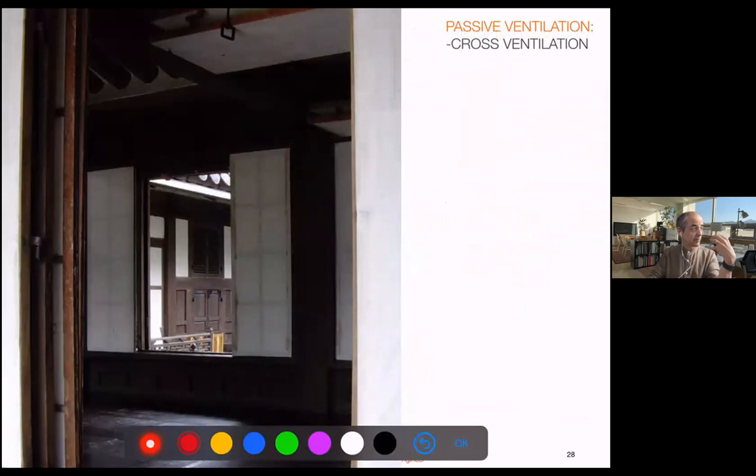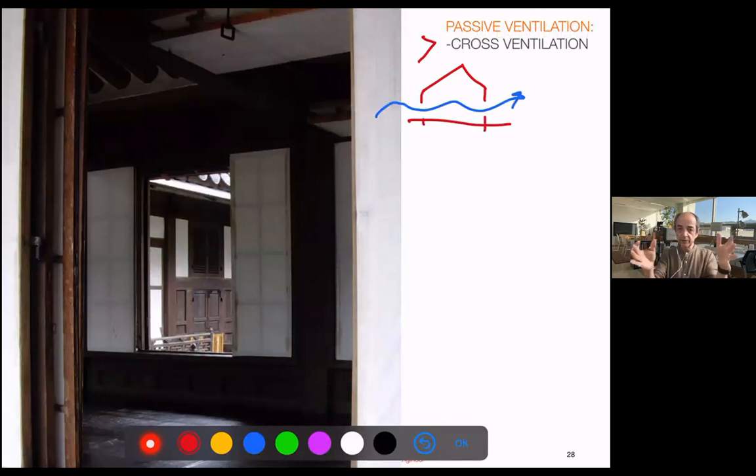Tips, especially for climates as extreme as Korea, in summer is the cross ventilation. So if you have a building and you can have the air crossing from side to side, you will always have some air movement. It will be easier for the air to renew. This is why rooms with two windows in different orientations, something that, for example, Frank Lloyd Wright did very often, right? He tried to make important rooms with 2 or 3 facades. Also, you will have one space with sunshine, heated, another cooler, and that will make also some kind of air movement. Probably in that case, the movement would be in the opposite way, right?